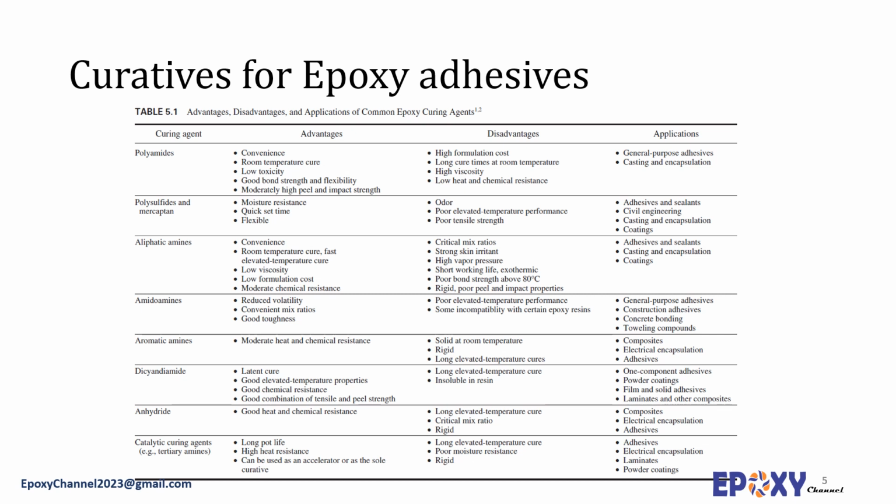Concerning the thermal stability and the high temperature limit of the cured adhesive, the Tg of the system is the predominant factor, which is dependent on the type of epoxy resins, the employed curing agents, and the employed curing regime. Higher Tg values, for example 250 to 300 centigrade, can be obtained while multifunctional epoxy resins and curing agents with hot cure temperature regimes are employed in the formulations.